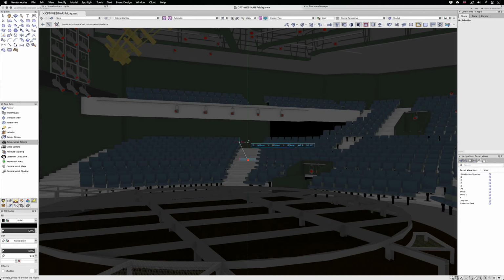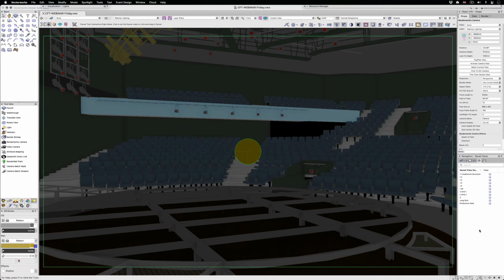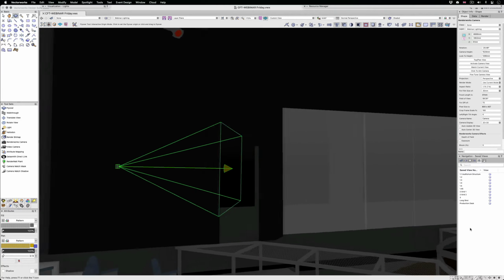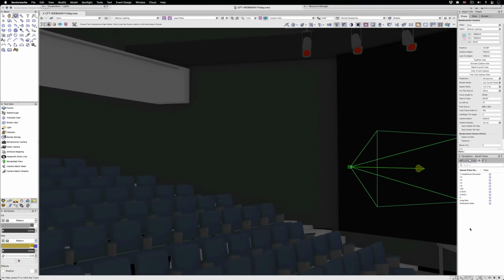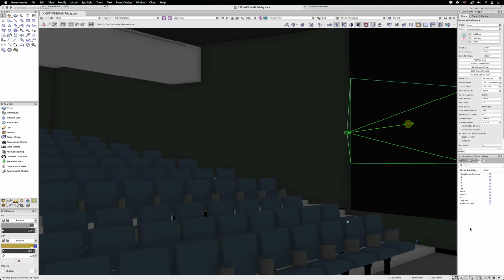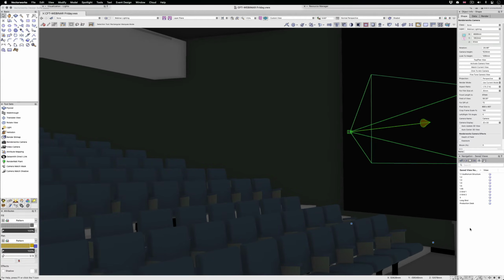When you add a RenderWorks camera, you can put it anywhere. Make sure you don't activate it though, but just click on the Match Current View button and the camera will align itself to your screen. Then all you need to do is navigate away from the camera and you can get a much better idea of where the seat was that I was viewing from. In actual fact, although it is close to a seat, it is not in an actual seat.